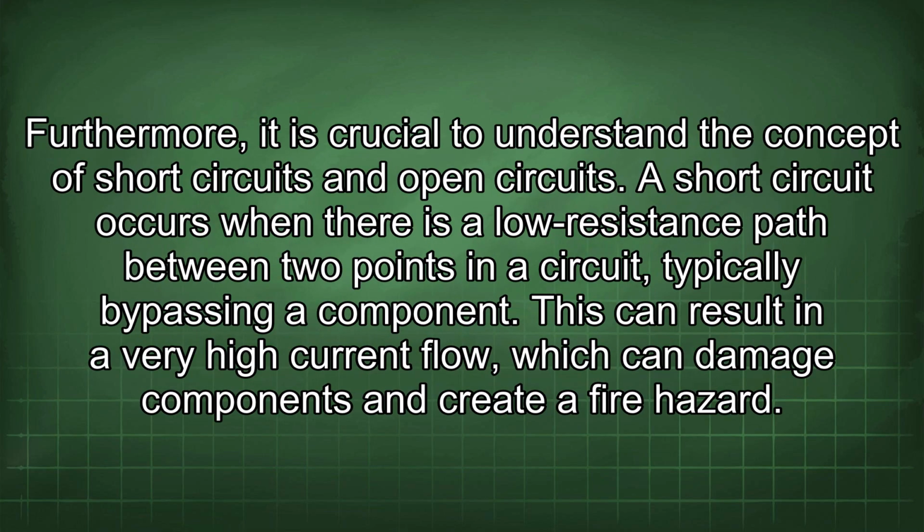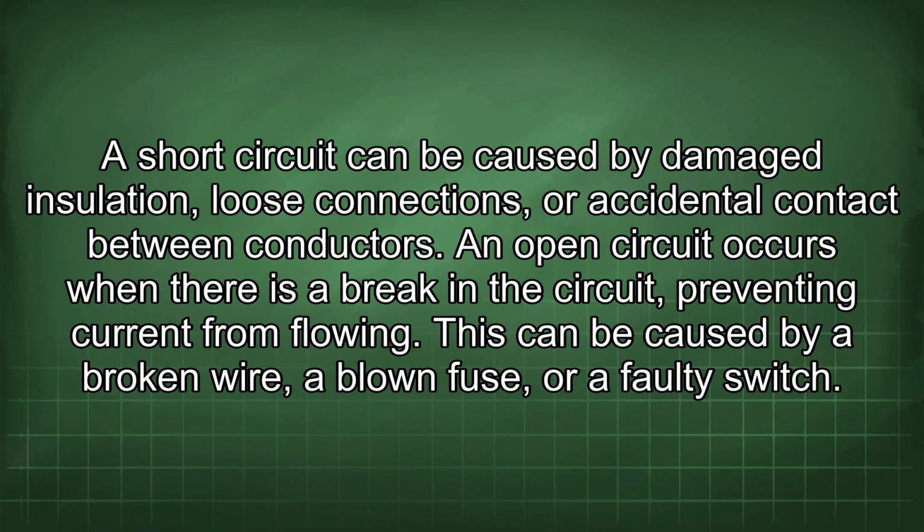Furthermore, it is crucial to understand the concept of short circuits and open circuits. A short circuit occurs when there is a low resistance path between 2 points in a circuit, typically bypassing a component. This can result in a very high current flow, which can damage components and create a fire hazard. A short circuit can be caused by damaged insulation, loose connections, or accidental contact between conductors.